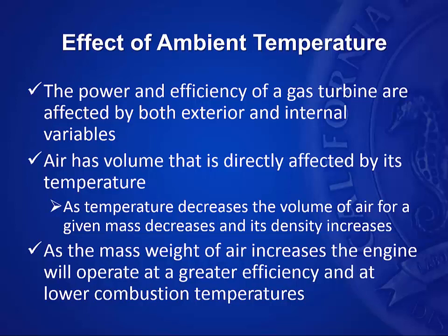So as you decrease the air intake, you will not be able to burn quite as much fuel, but you will also have to decrease the fuel rate to keep the temperatures in line, because the temperatures with a decreased mass flow rate will tend to increase.